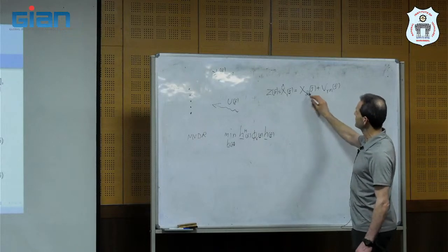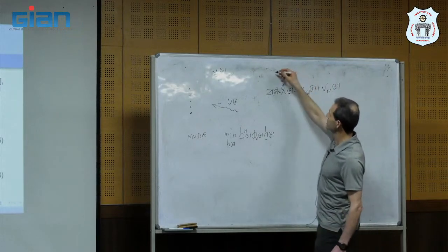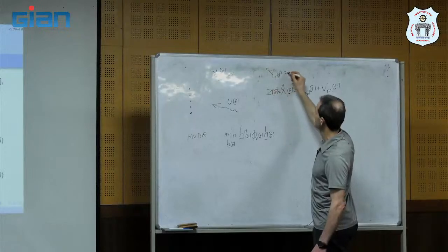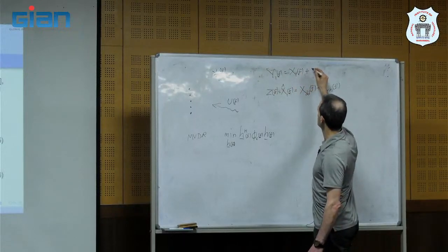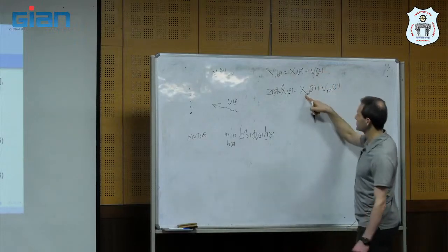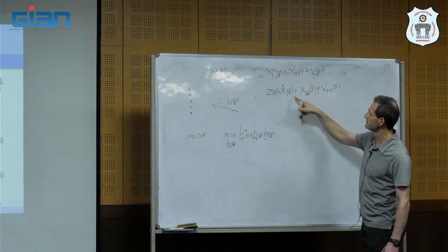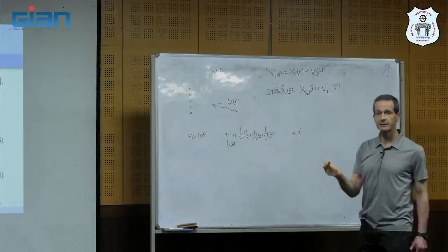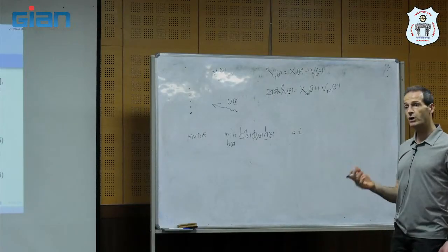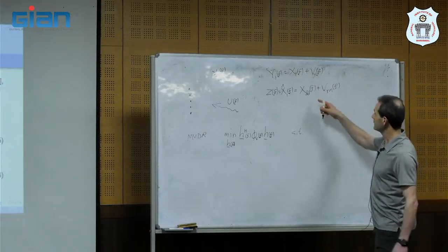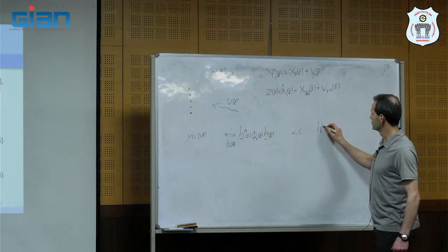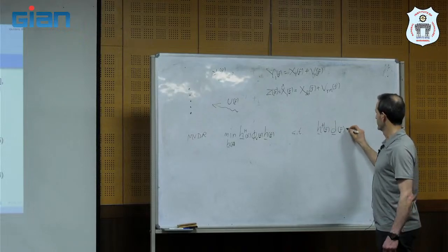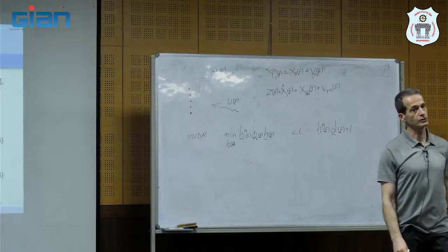If we want the filtered desired signal to be equal to the original signal measured in the reference sensor, X1(f), so that we don't have any distortion, we need the distortionless constraint, which we showed is H transpose conjugate d equals 1.